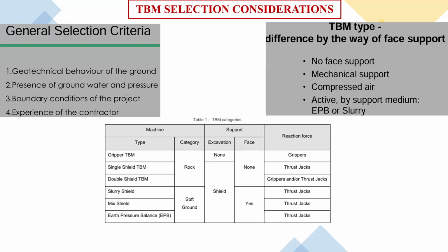And if the surface settlement is very high, then it creates a disturbance to the structures lying above the ground. So controlling the volume loss, keeping it to a minimum, and also installing the segments after the excavation and doing the grouting parallelly, to control the groundwater and also fill the gap between the segments and the ground. So this is the experience of the contractor. All these characteristics we combine, and then the contractor, the consultant or the client jointly make a decision on the particular TBM.